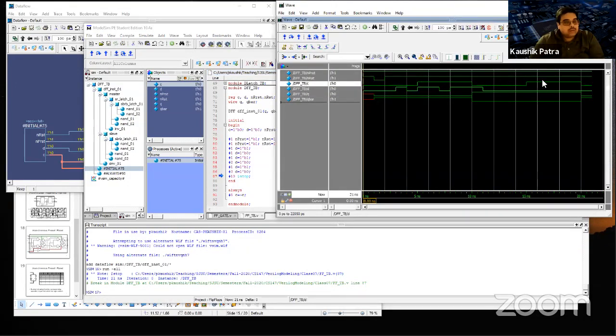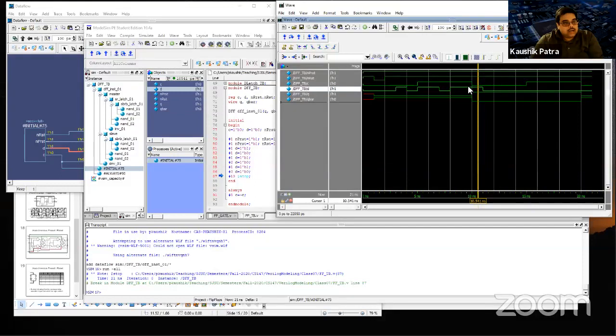Now we are moving from the control signal to the clock signal concept, where we are changing this clock signal value at a constant interval of time. And then we are toggling the values on the D input side and seeing when Q is following the D. In this circuit configuration, only at the falling edge, Q follows the D value.